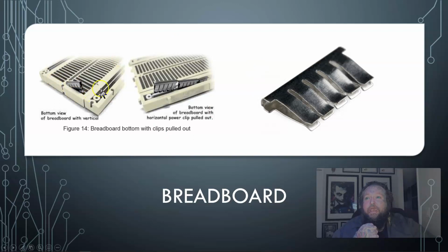Inside of them you get that insulating plastic material on the outside, and you have a whole bunch of little holes, but inside you have these little metal clips. The idea is in that hole you'll plug in an actual wire, and this clip will hold it. But all of this is metal and all connected together, to allow the flow of electrons through the actual circuit. So wherever they are, it's this entire line.